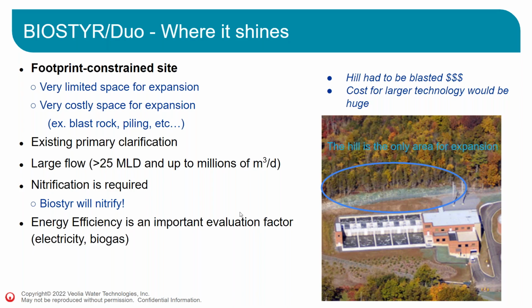It's also a good project when there's some nitrification required, because the Biostyr can do BOD and nitrification removal in one single cell. So there's only a need for one step. You don't need two steps to do both. And it's an energy efficient technology. I will talk a little bit more about this one later on.